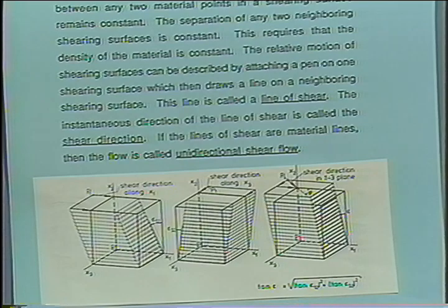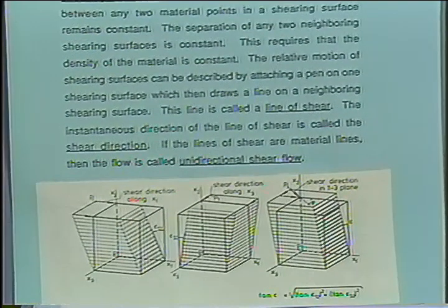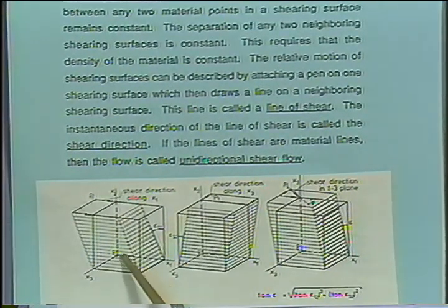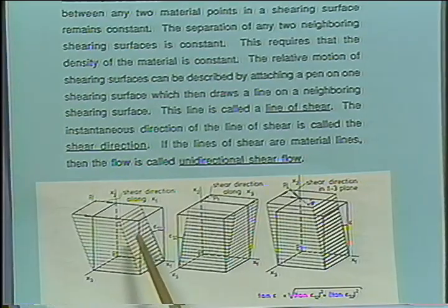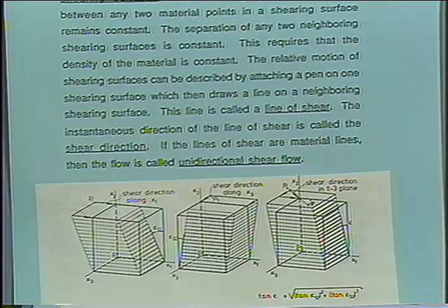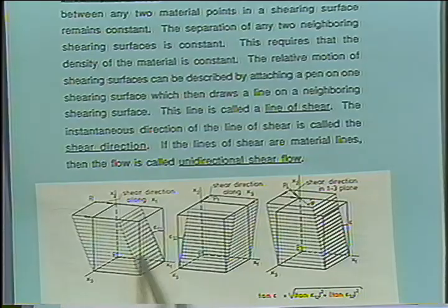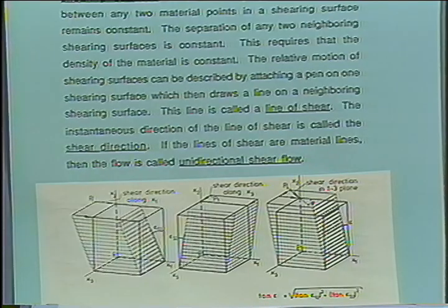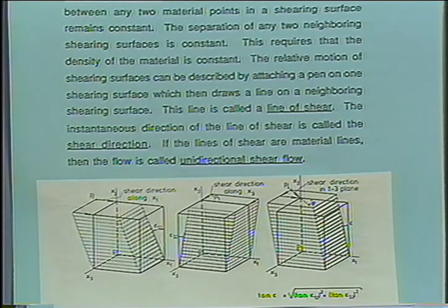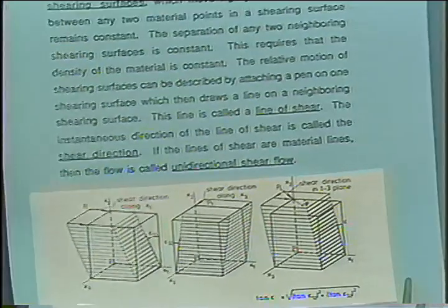Therefore, for steady shear flow, which we will define later on, we will require a constant shear rate in time, and secondly, we will also require a constant shear direction that cannot be altered in that experiment. That will be then for steady shear and for discussing material functions in steady shear.